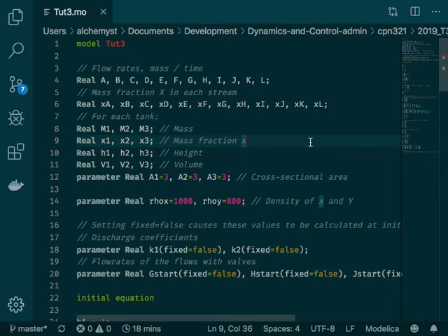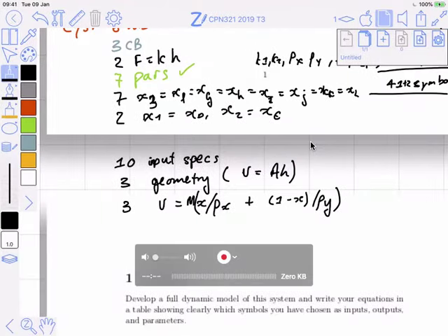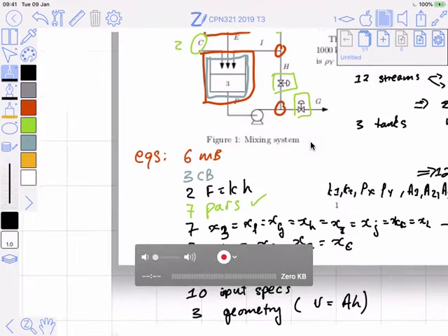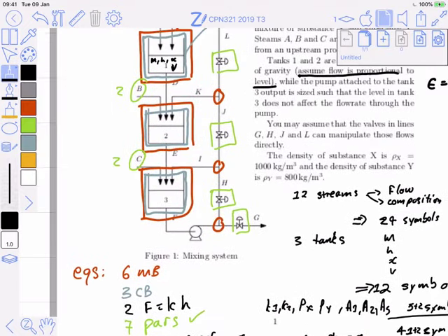For instance, if I did a mass balance, the exact context would be something like, remember I said you can't do a component balance and specify equality on all of these nodes. How did I know that? The answer is that, unfortunately, the math itself won't tell you. Just by itself, there's no easy way to count dependency. In modeling systems like Modelica, once you actually start modeling it, that will tell you that there's a singularity in the equations.